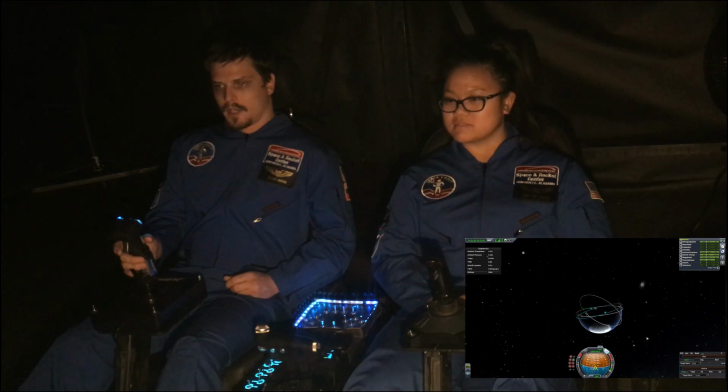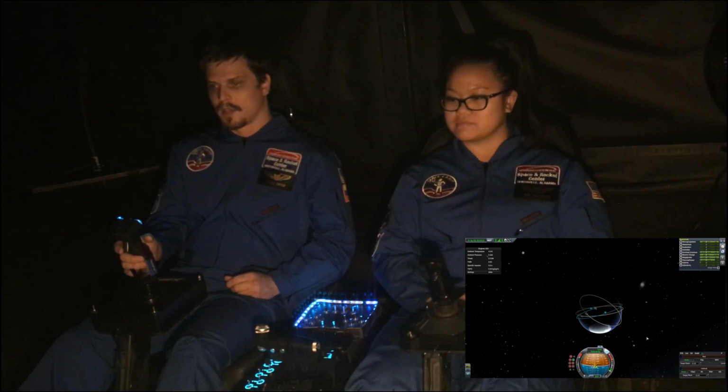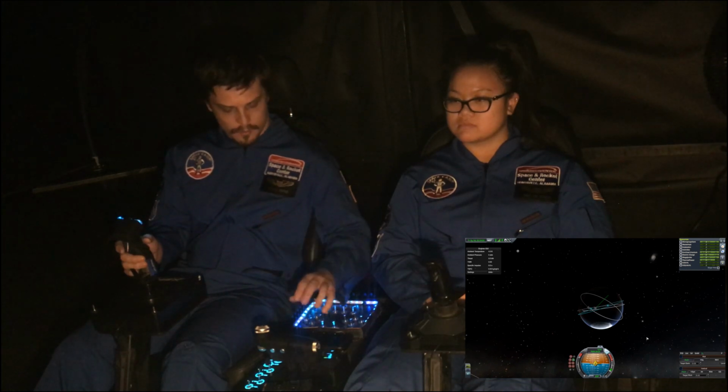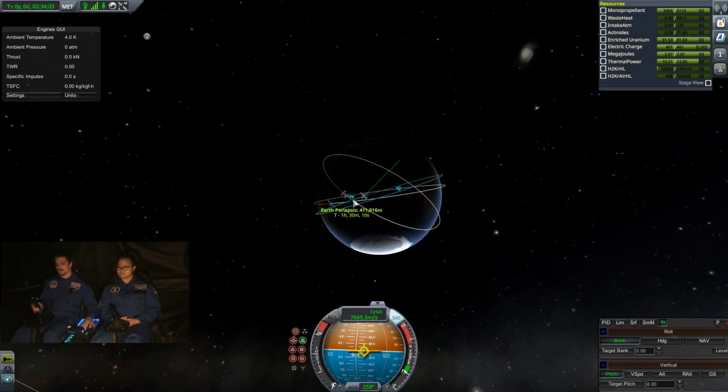Alright, so we're going to go in our retrograde direction. Retrograde means we're going against our orbital direction. Prograde means we're going with it. So retrograde means that we're actually going to decelerate. So before we decelerate, we just want to see what our periapsis and apoapsis values are. So now we're going to slowly increase our thrust, and we're going to bring down our periapsis to about 50 kilometers.